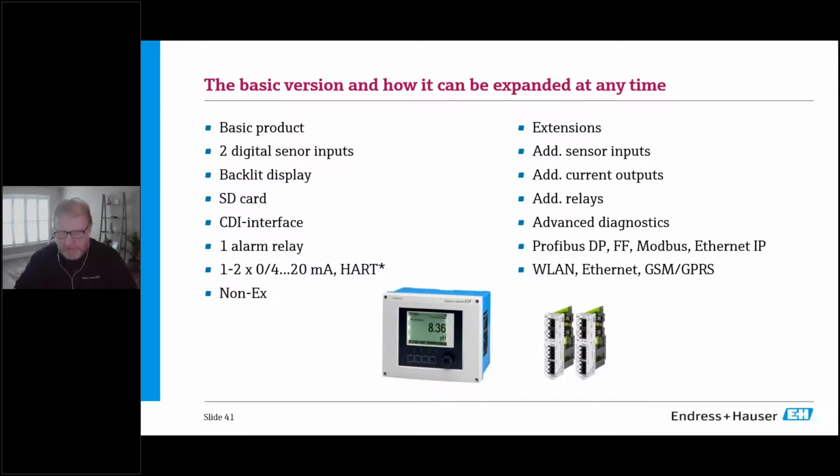So what that means is if you have this transmitter tied into a Rockwell ControlLogix or a Rockwell PlantPAx system, our engineering department works with Rockwell's engineering department prior to us releasing a product, and that product then will have all the add-on profiles, add-on instructions, and faceplates, so that when you connect it to a Rockwell controller, it knows it's talking to an Endress+Hauser pH probe or a DO probe.